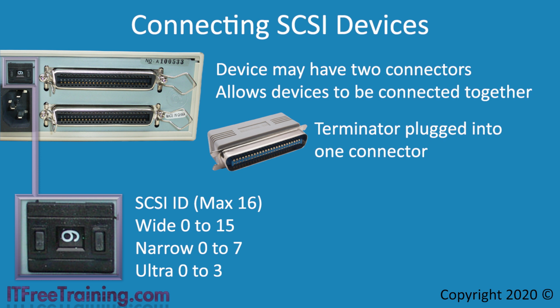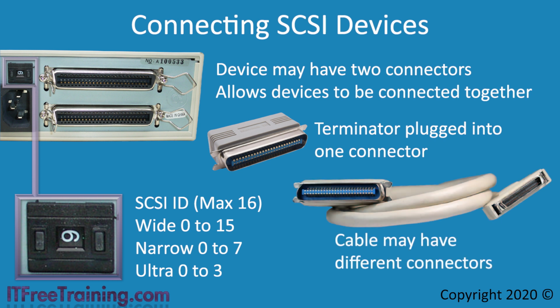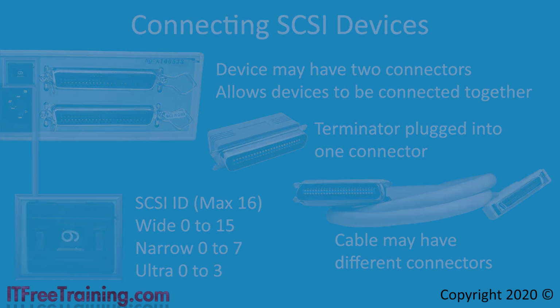When connecting SCSI devices, your cable may have different connectors on the end. If one is a wide connector and the other narrow, this will reduce the number of SCSI IDs supported by the cable. Besides the speed of SCSI, there were some other features that made SCSI popular despite its higher price. Back in the day, SCSI was used more for high-end workstations and servers. There were a lot of reasons for this, besides its just being faster.